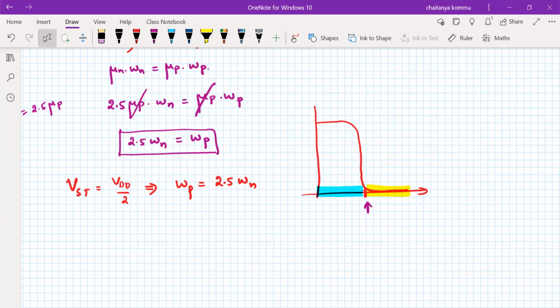Okay, so that means whatever PMOS transistor you consider here, for example, suppose I have taken 1 unit here, then how much should WN be? It should be 2.5 times this. For example, if I take 20 here, then 2.5 times of 20. That is the size ratio that we have to maintain. If you do not maintain the size ratio, the symmetrical operation cannot be possible.